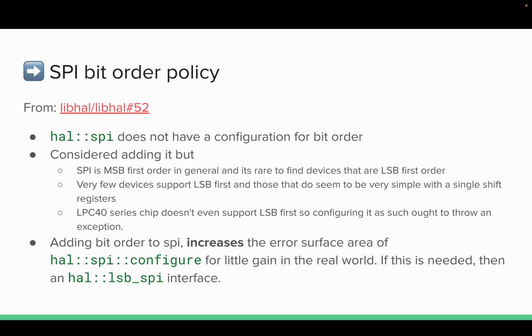I wonder how many devices actually have LSB first. Because if half of the devices out in the wild use LSB first, then it's kind of critical that we include it. If more devices do that, then maybe I need to consider LSB first as the default. But actually, I considered it, then did a little research. I asked ChatGPT, and I also just Googled around. It seems very predominant that SPI is MSB first, and it's rare to find devices that are LSB first.